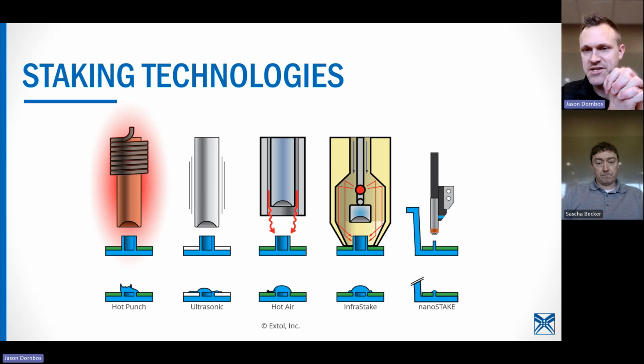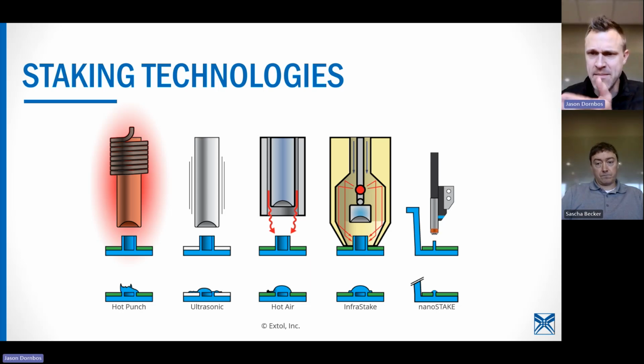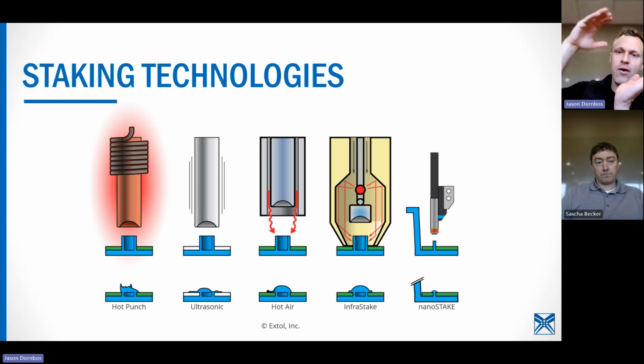It's a mechanical retention. So here you might not even have two plastic components. You might have one plastic component. It's got a boss on it, something standing tall. And then the other component has a hole or some type of a mating interface. The boss goes through the hole, and then you form the top that's coming through to capture that mating component. That mating component could be another plastic part. It could be a printed circuit board. It could be a metal bracket. It could be a whole lot of different things, but you're forming a head over top of that mating hole to capture it and keep them together.